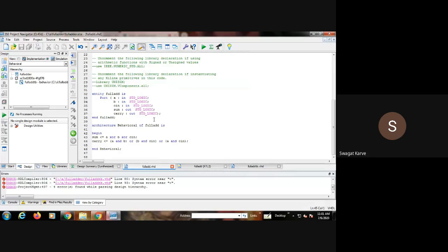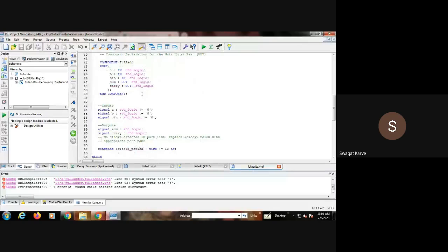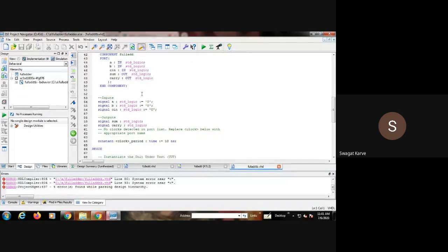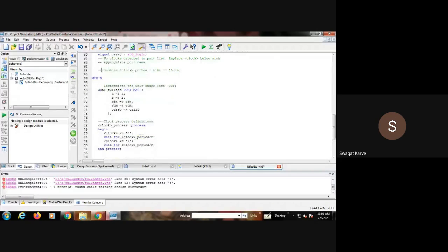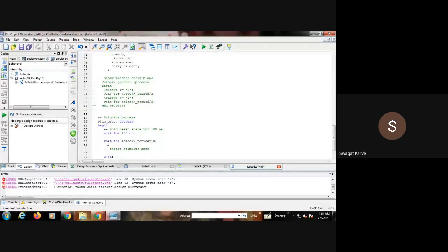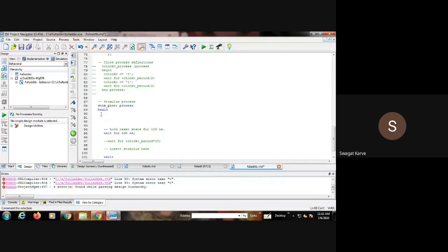बघा आता खाली इथे आपल्याकडे 3 आहे. This is our original code, this is the VHDL code, this is the RTL equivalent design that we also have, and this is the test bench code. Now in this we are supposed to test our circuit. Okay, now here we have to write the different test cases.